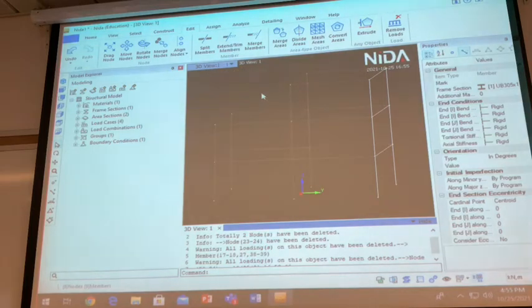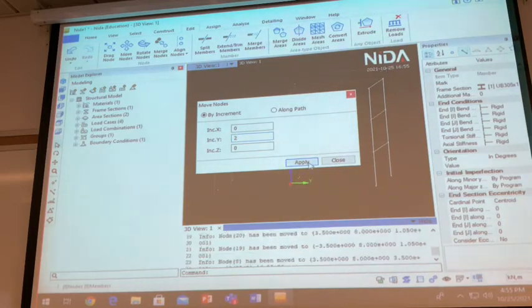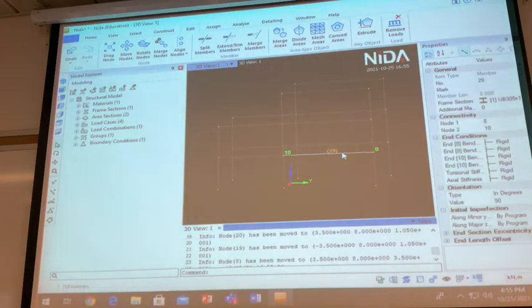Okay. So I select, I highlight the element, and then I want to move the loop. So I will go to move loop. I want to move it in the Y direction in this way by 2. So 2. So you can see, and then I check it. Yeah, this is X beta, and this is the 6 meters that we defined from the template. Now the geometry is quite done. Alright? The geometry is quite done.